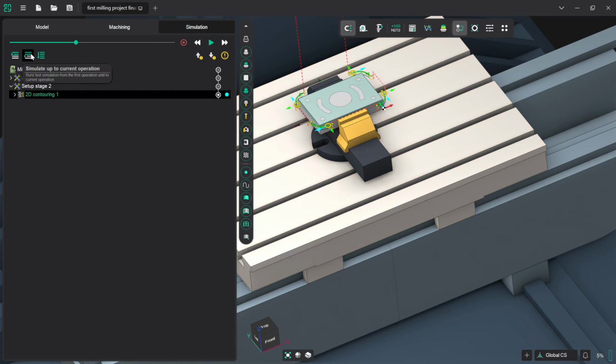So we've got a good lead in there, and it's taking off the edge of the material exactly as we intended, and a nice lead out. So it's safe to say it's going to repeat that pretty cleanly 4 times now. And there we go, we've managed to cut our outer edges without having to use the entire exterior contour of the part. Very quickly, very easily define those parts.